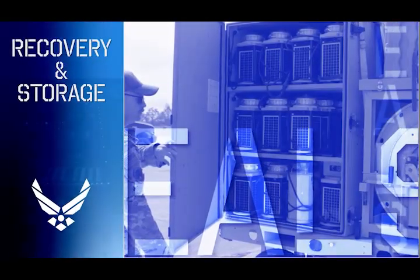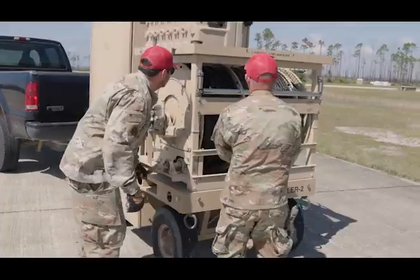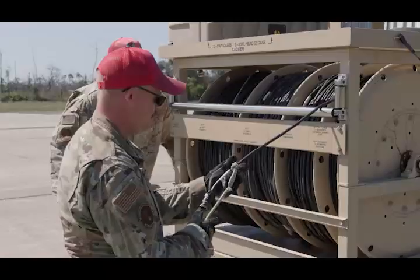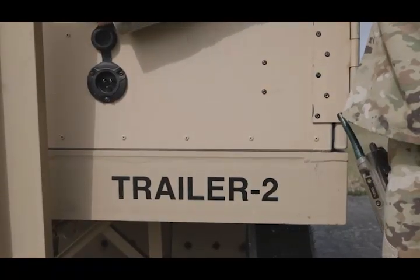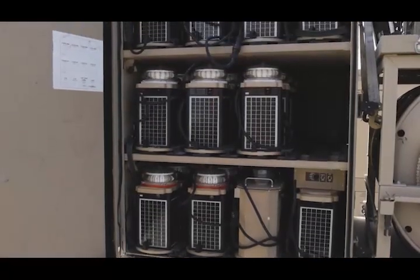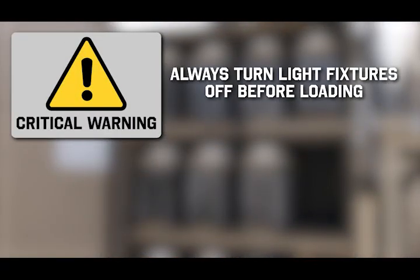Recovery and storage. When it's time to recover the EALS, reverse the deployment sequence, recovering lights at the end of each parallel run. Make sure the sockets are on the reels first. Avoid dragging connectors to limit wear. Each trailer charges fixtures using standard 90 to 270 volts AC wall outlets. Each rack level operates as an independent charging circuit with daisy-chained lights. Critical warning: always turn light fixtures off before loading. Leaving them on damages battery life.